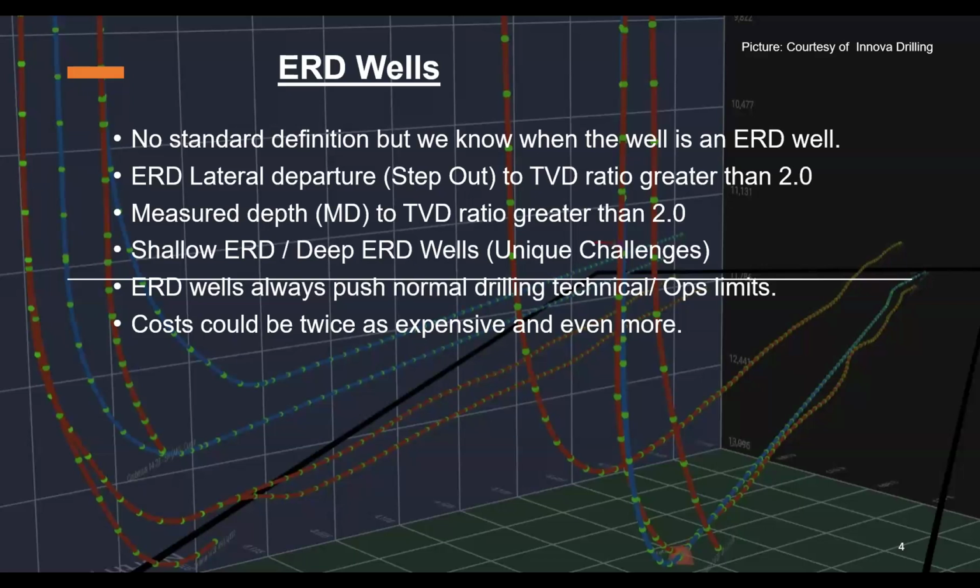You are drilling in certain areas where they do not have any surface processing for sand separation, or getting rid of sand from the oil. And you are designing a well in that area where they did not have a lot of problem with sanding. Sand is not coming with the oil, but would you like to have some sand screen or sand protection technology? Yes, probably yes, because if sanding comes, the whole well will be junked. This 80 million will be gone.